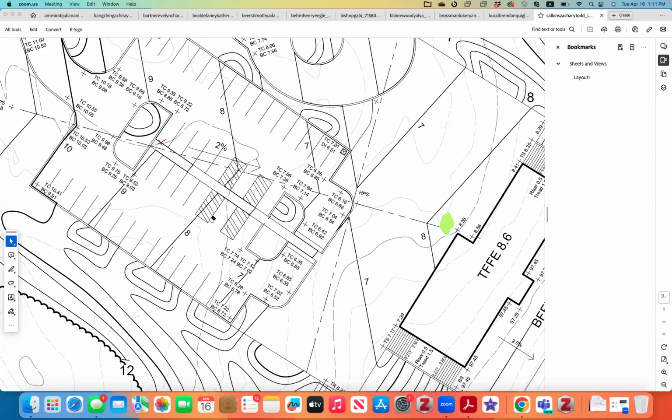But I personally think having a sidewalk all the way along that is on top of the curb is a better solution. It doesn't take much to do the curb ramp over here. I would just do a curb ramp, and then honestly, I would put the 2 shadings together. So it's better if you put the ADA sign, so if people are parking here and there.